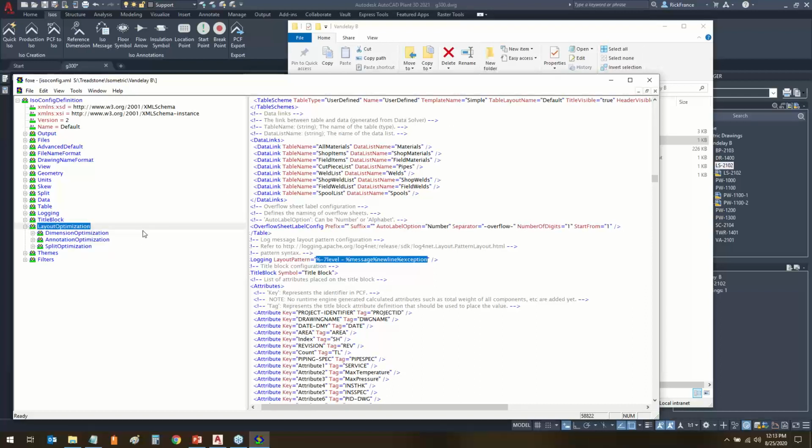Layout optimization. This is for optimizing the annotations, dimensions, how much information goes on the drawing. Again, all that is in the project setup. Tweak it there, because if you make one little mistake on something here that you can do, which you can do in the project setup, you're going to really mess some things up. I'll give you an example.